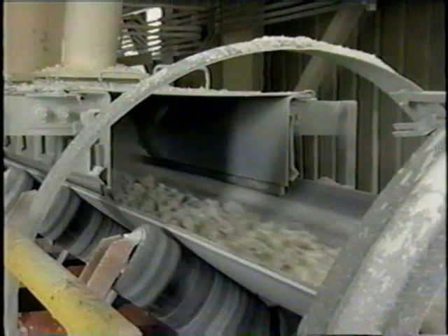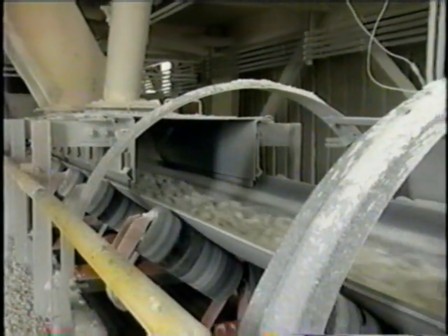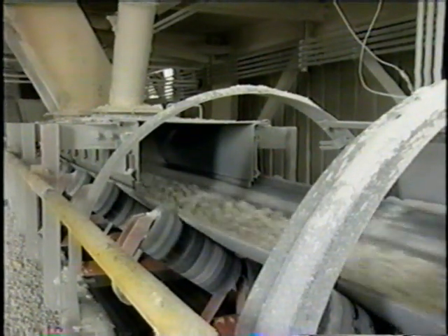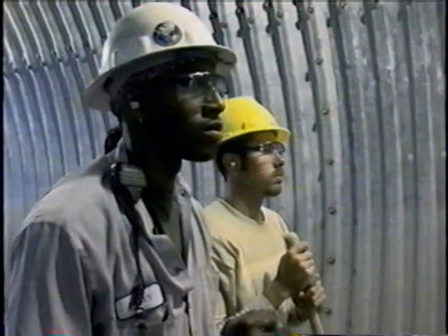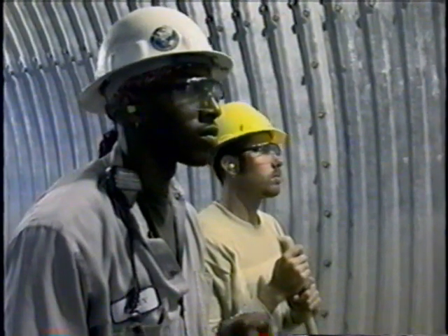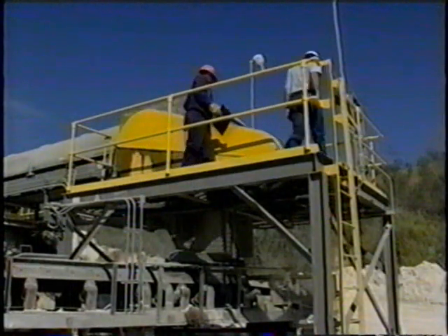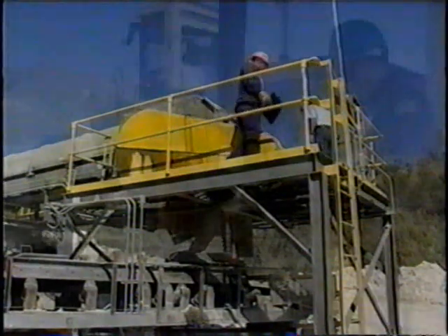When inspecting this area, is the conveyor equipped with either an inside handrail or emergency stop cord system with the cord in good repair? Can the remote startup alarm be heard properly, warning that the belt is about to start up? Are all guards properly in place?